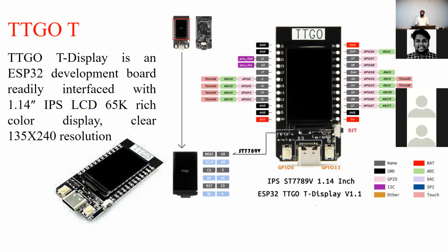That is the best option for implementing your embedded and IoT platforms without machine learning applications and artificial intelligence. The only drawback of this hardware system is that it does not have any operating system or real-time operating system, and the applications of machine learning and deep learning may not be completed or executed successfully using this TTGO-T. Okay. By adding some hardware modules like camera devices, it can also be used for video processing applications or machine learning applications, but the performance may be degraded.